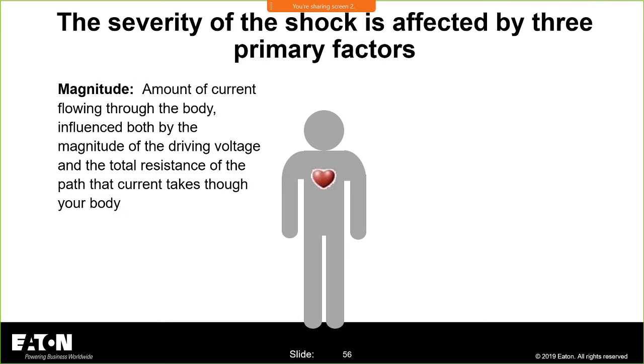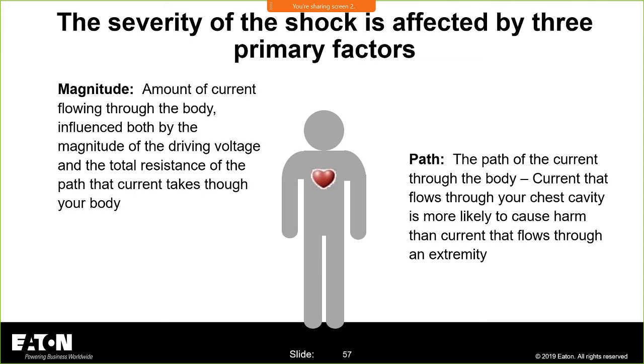Now let's talk about the hazard of shock. The magnitude of current that flows through your body is important. The path that current takes through the body is important. If it goes through the heart, it's much more critical than anywhere else. And the amount of time that I let that current flow through the body is all a part of shock.